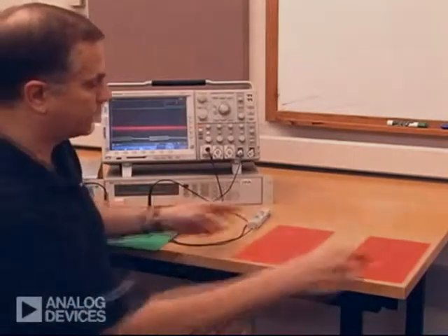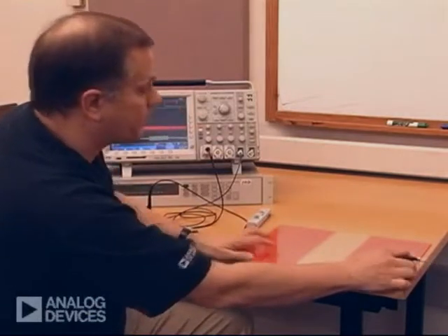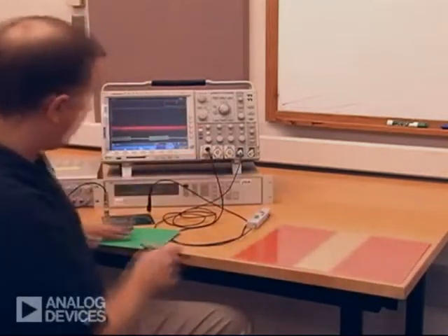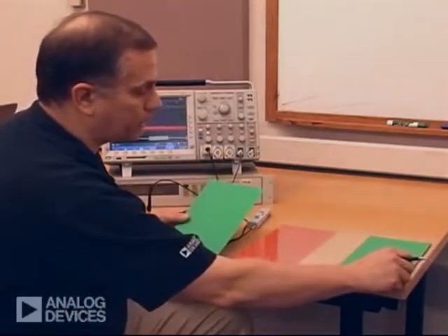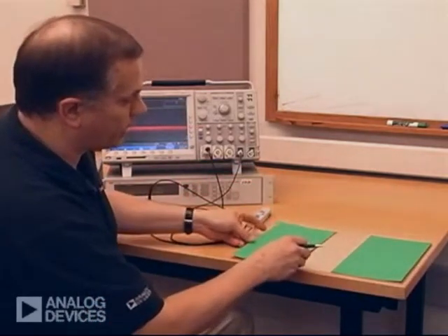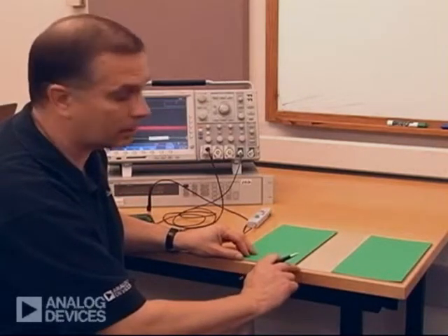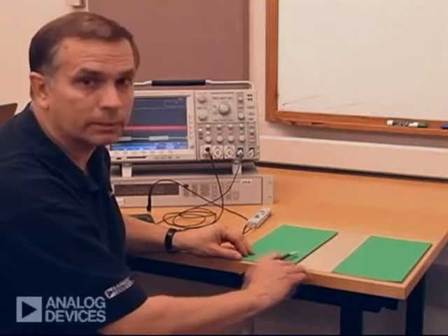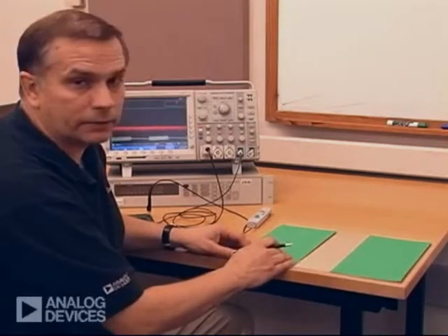We'll use this clear plastic as the circuit board material itself. Now, if we place the ground and power planes very close to each other, right on either side of a very thin layer, and standard PC boards can be as thin as 4 mils, this creates a very effective low inductance capacitor on the input side and the output side.